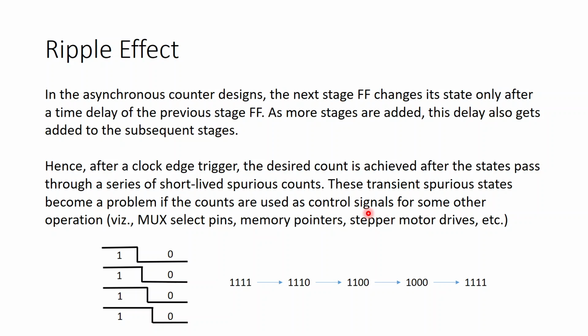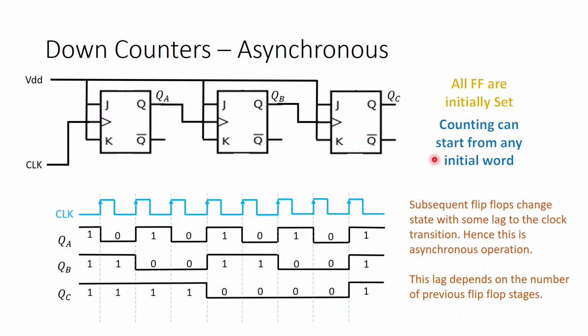So when we are trying to change from 000 to 111, this is changing, so it takes some time to change, and after that change only this will change, and after that change only this will change. So there is always a lag. Though we denote it at the same instant as the clock because the lag is very insignificant, still there is a definite lag.